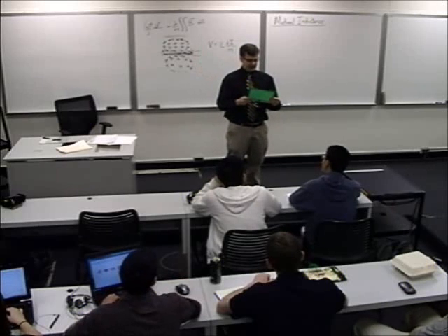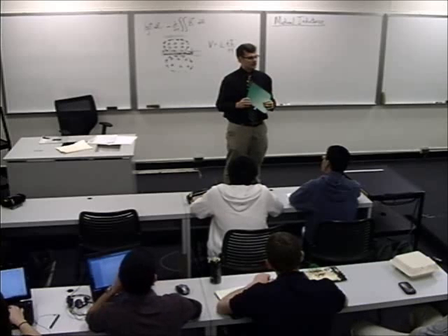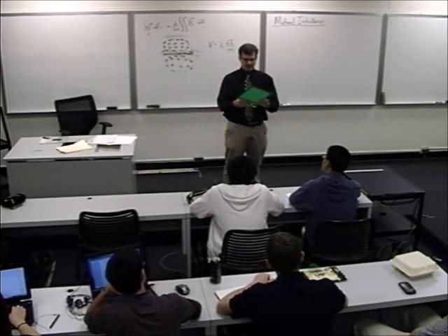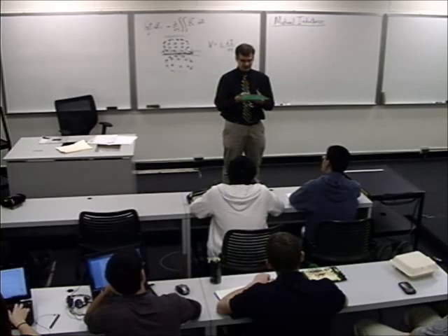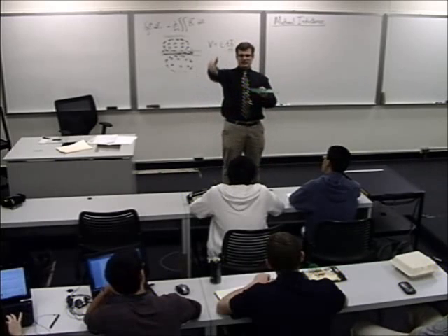This is actually an RFID 13.56 megahertz inductive antenna, or reader coil. It doesn't really radiate, so some people wouldn't call this an antenna, but a lot of people in the trade call it an antenna. And what it does is you send current around here, you make that beautiful H field solution that circulates around.